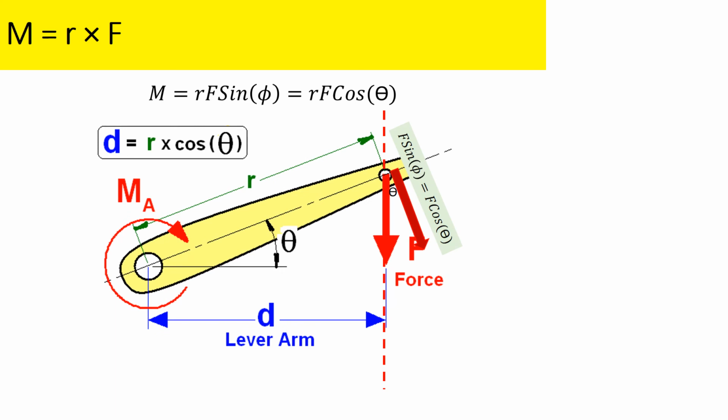Another way to break it up is to figure out which piece of your force is perpendicular. So if we draw the position vector and then just draw a line perpendicular to that right through where the force is acting, we can split our force into which piece. This is kind of like a normal and tangent component of our force. So which piece is perpendicular and which is not, and it's the same exact equation, it's the same numbers, it's just a different way of looking at it.